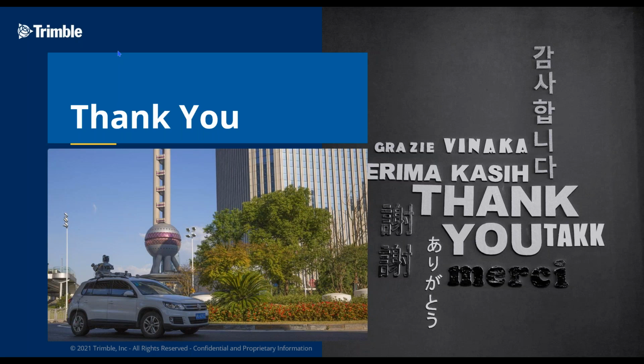Can TBC handle photogrammetry work such as orthomosaic and 3D model and publishing? Yeah, TBC is now not handling the photogrammetry work for MX9 in the same way as TMX does. So we would recommend TMX for photogrammetry work with MX7 or MX9. And the 3D model obviously can be brought to TBC as well. TBC does not provide the publishing option, but it links to Trimble Clarity, where the point cloud can be visualized and shared.